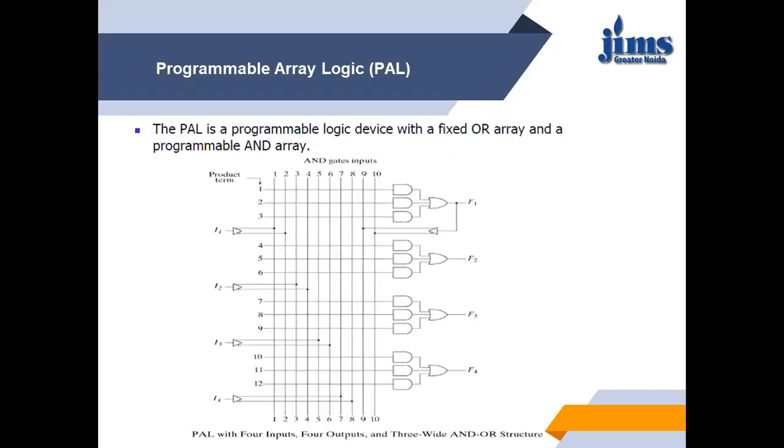You can see that in this particular example we have four inputs, I1, I2, I3 and I4, and with these four inputs we have 8 input lines: I1, I1 bar, I2, I2 bar, I3, I3 bar, I4 and I4 bar. The major difference between PLA and PAL is this. We have 2 extra input lines, and these input lines are nothing but F1 and F1 bar. So the first output of the OR gate is fed back as an input, and we have to find the optimal Boolean function in such a way that we can minimize the number of